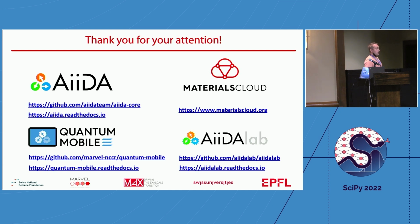Yeah, so for the precision, as you say, it's the energy accuracies for Quantum ESPRESSO, say, the basis set selection, the number of k-points, all of this trying to balance the level of accuracy versus how long it takes, with fast, moderate and precise. So the idea is that it should only take a few minutes for the fast, and then precise is your kind of production runs.